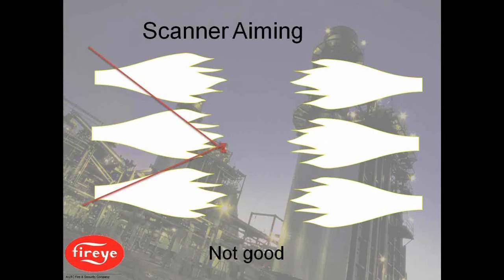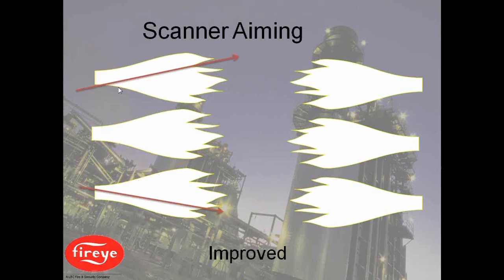Here's scanner aiming. If this was an opposed fired furnace, again, a 6-burner type application, we could see that we've got a not very good situation here because we're going to be at high fire. There's just going to be a ball of fire in there. We're catching some of the primary combustion zone on this one, not very well there.